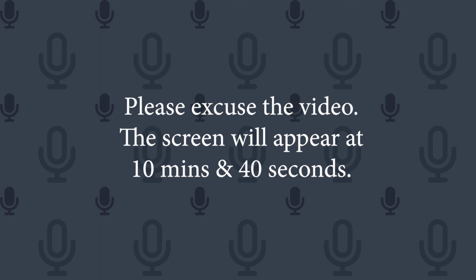So let's start in detail with step one. Turn on the pulsation frequency analysis module. The PFA module will not be active by default. If you want to use it, you need to activate it. So first you have to select and activate the modules from the tools menu and check the PFA pulsation frequency analysis.